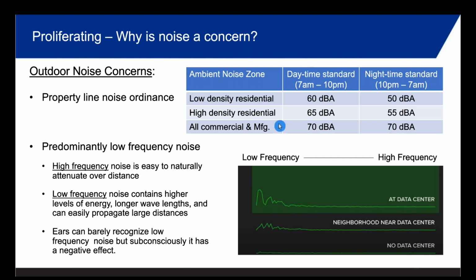And that shows in the chart to the right here. If we look at low frequency on the left and high frequency on the right, at a data center, what you find is you have, after all the systems are running, you tend to have this low frequency noise issue. This is true for other industries as well, but in particular, since we're talking about data centers, this can happen. So it's not that they're unique, it's just something that can happen. And we're talking about frequencies a lot of times down here that you really can't hear, but you can measure. Okay, you can measure it with a sound level meter, but you can't really hear it.